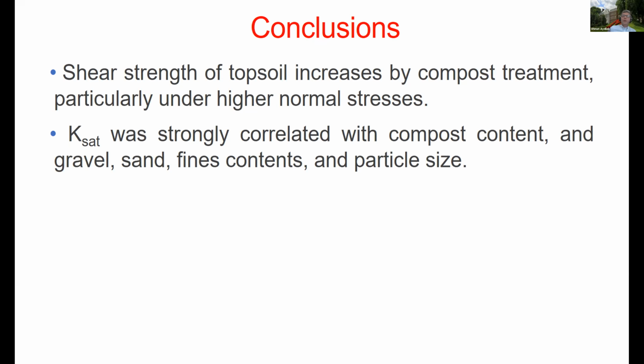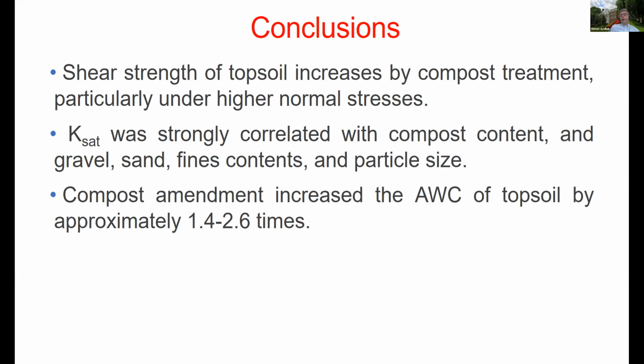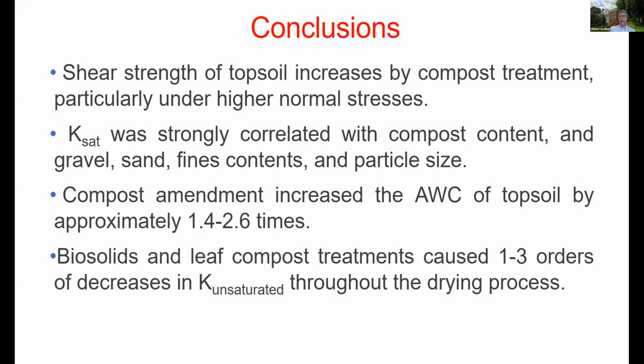If you look at the United States Department of Agriculture chart, they would not use that. So if one wants to follow strictly the USDA chart, then those terms can be modified as well. I was directly following the Unified Soil Classification System. Compost amendment increased the available water content of the topsoil, which is very important for plant growth. And also the biosolids and leaf compost treatments decreased the K values in the unsaturated zone by about 1 to 3 orders of magnitude.